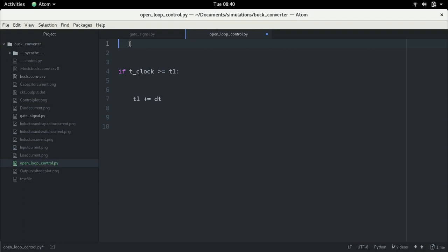One strategy is you are going to change your duty ratio once in every carrier waveform. So in every sawtooth waveform, that is when it starts from 0 goes up to 1, in that one cycle you change it once, right? There's no need to change it more than once, just once. There are of course some other strategies where they change it once in every few cycles. So it may be once in 2 cycles, once in 5 cycles, so on and so forth.